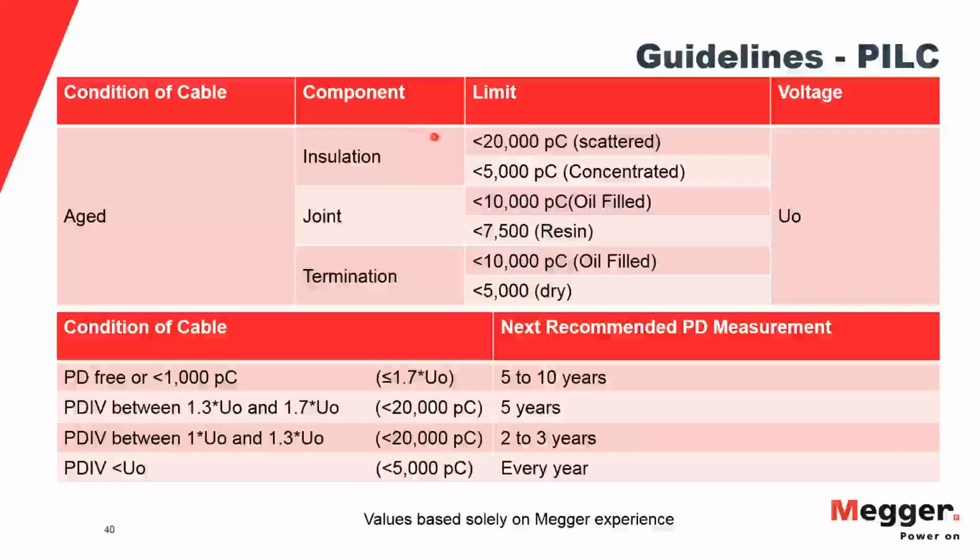On top of that, what you typically see on those cables is that pretty much all of them, with some exceptions, but you can say with little inaccuracy, show PD at operating voltage, and their extinction voltage is much less. So people over there, in terms of lead, are not even concerned about the extinction voltage because they have PD anyhow. So this is how these numbers are collected: experience values from utilities, related to the infrastructure as it is there in Europe.